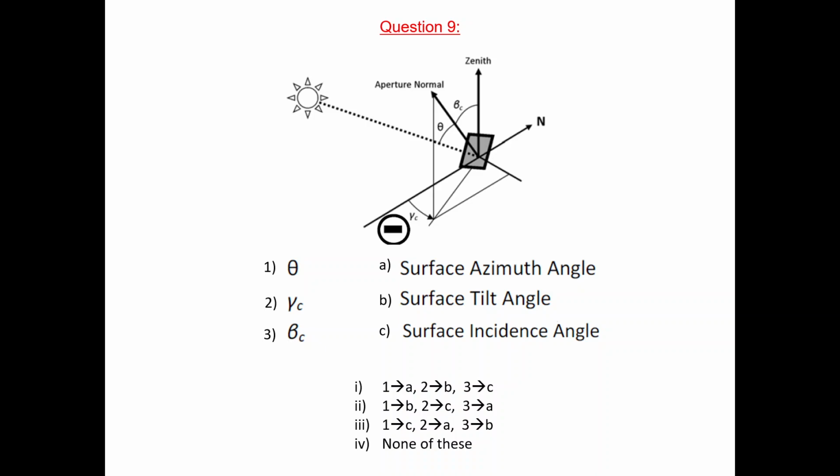Now, why are these materials important? Because we can play with their band gap. We can dope some element in them, we can extract some element, we can create vacancies, we can change dimensions, and changing all these parameters changes their optoelectronic and photophysical properties. They change their absorption and their emission. Suppose you create a vacancy, and a material that was emitting in the yellow region starts emitting in the orange region, and you can utilize it for certain applications, and the whole electron carrier dynamics change. So these materials are in very high demand nowadays.